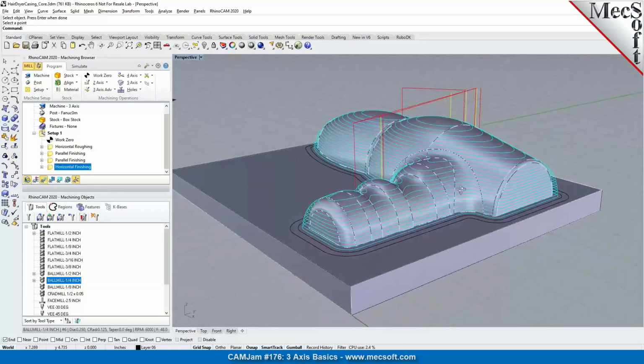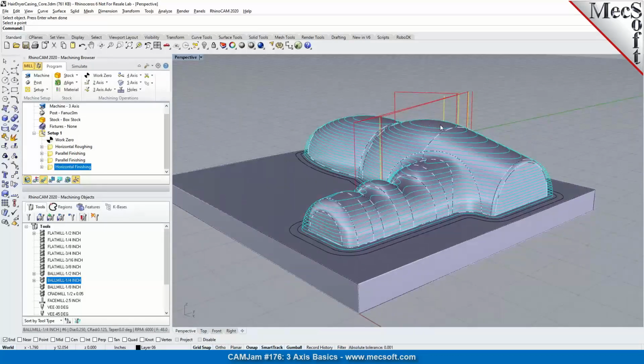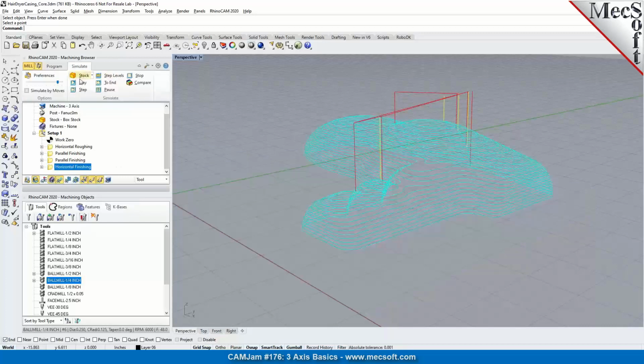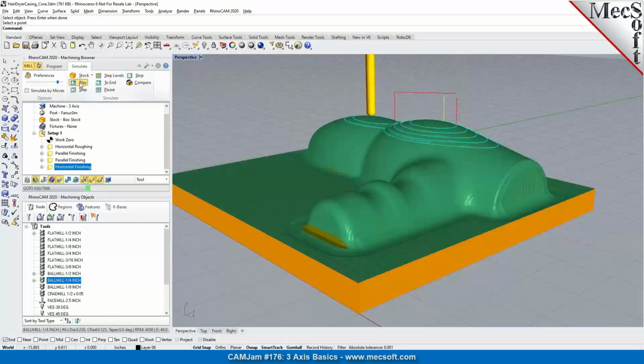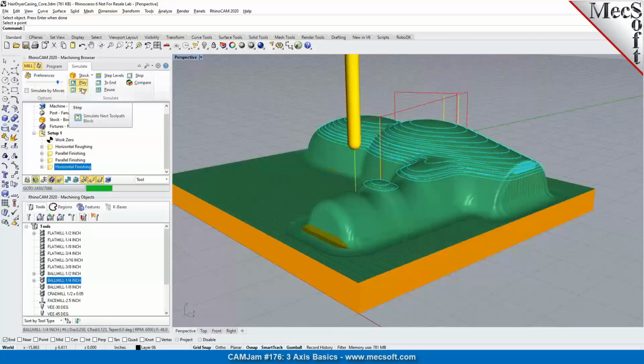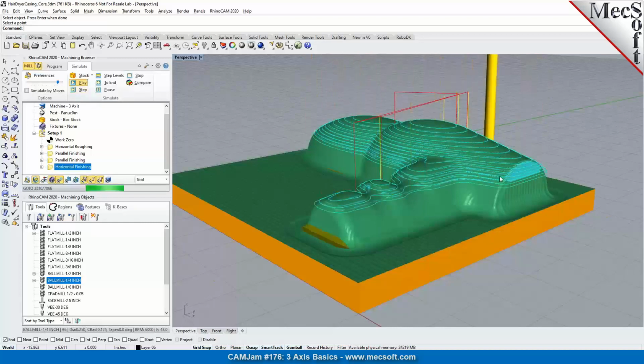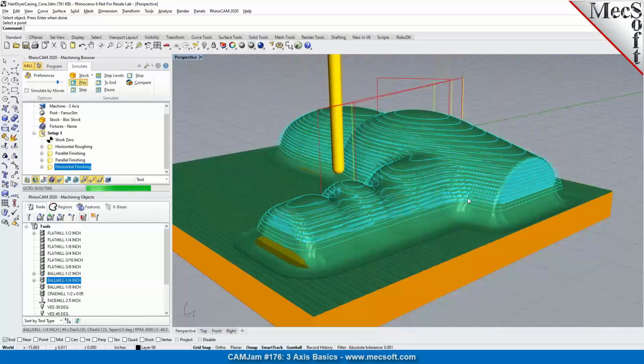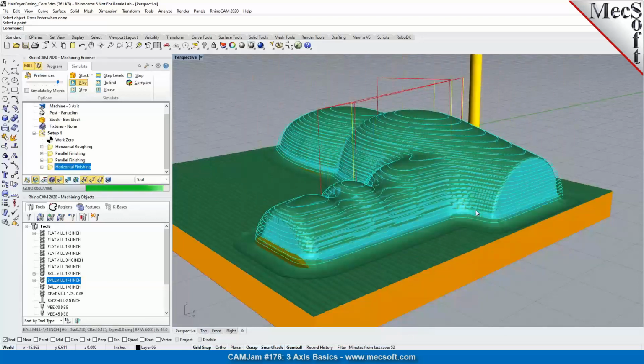So you're noticing here the toolpath generator is known as horizontal, or also called Z-level finishing, where it's generating constant Z levels. I'm stepping through the Z-level display, and as you can see, the toolpath displays in levels. So this is a good technique to program steep areas in your 3D models, and this will go ahead and take care of cleaning up all of this scalloping that was left in the steeper sections on this particular core mold.